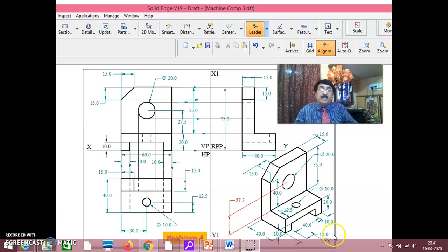Along with this, see here, because when you're looking from here, this fold in the front view cannot be seen. It is invisible. The edges of the fold will be invisible. That is why, in the top view at least, this circular fold can be seen. In that way, I'll draw the circle in the top view, take the projectors up, and I'll show this portion, the pole is in this portion. That means you show dotted only here.